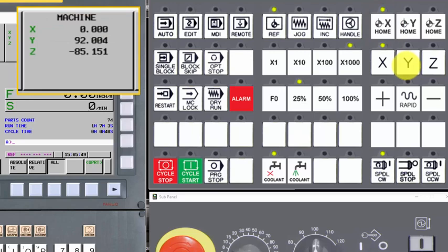Check the Machine Tool Builder's operator manual for specifics on the reference or home feature on a particular machine tool. With this particular machine operator panel, you can return an axis to its home in ref mode by selecting an axis and holding down the minus jog key until the machine position is 0. Note that the axes move at the rapid rate.